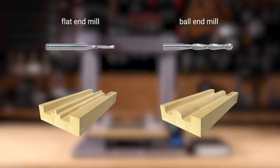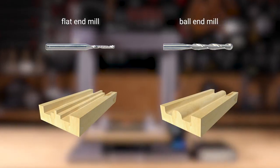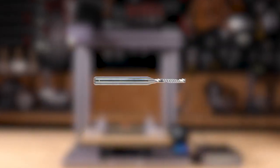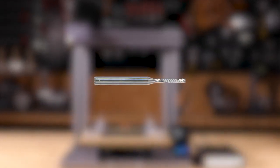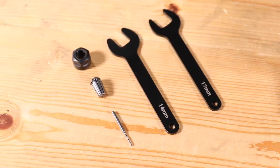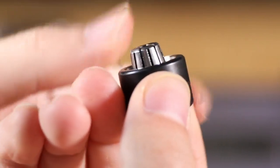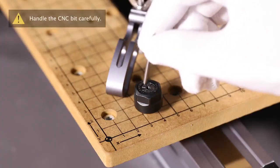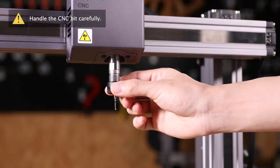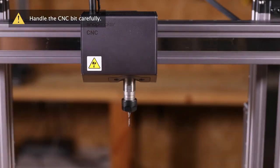Next, choose and install the CNC bit. Flat end mill is typically used for slotting or cutting materials with flat surface, while ball end mill is for carving materials into curved shapes. Since we are using acrylic cutting as an example, flat end mill is the better choice. So, take out the presented accessories and tools. Insert the ER11 nut into the ER11 collet until you hear a click. Next, put the CNC bit into the nut. Screw the entire unit onto the shank and tighten the ER11 nut using the wrenches.